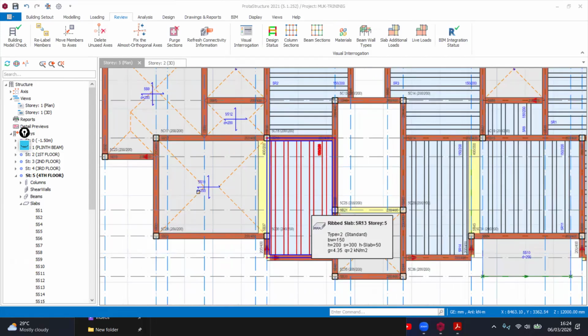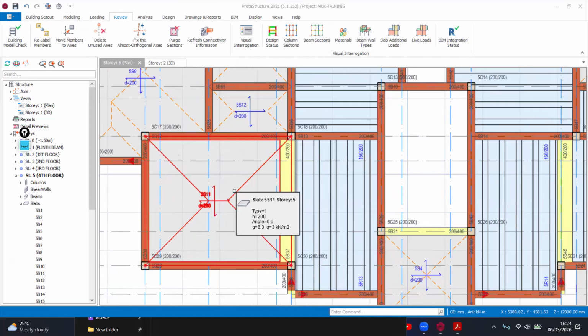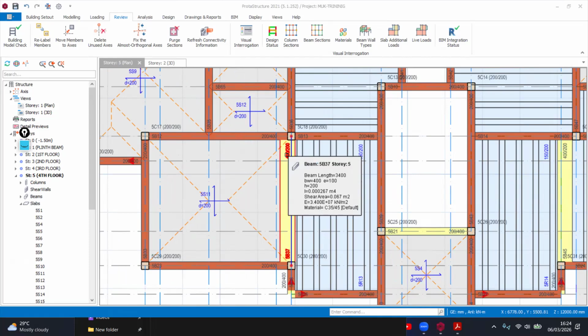Now, after you have changed it to this format, this means that this beam is carrying a load from this slab. For solid slabs, we are constrained to just the way it is. It's not like for hollow slabs, where you're going to change the span direction of those ribs. So we are forced to change this into a drop beam.